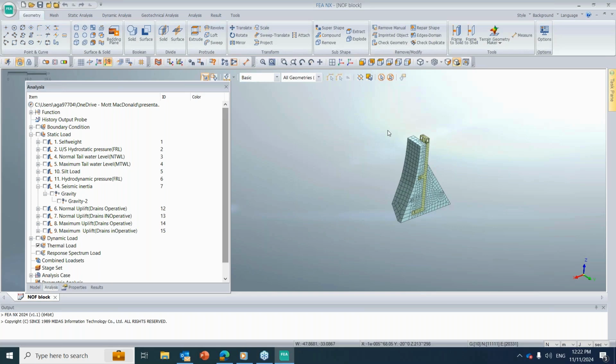If we go with thumb rules, your lateral boundary should be double the height of the dam and the bottom boundary equal to the height of the dam. We can also use that. These are general thumb rules.